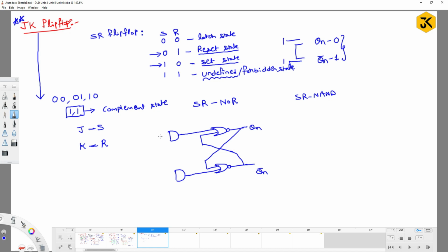We have seen the meaning of this also. As they are under single line control, meaning that at a single point we can control the entire structure. I can make it an enable signal or level signal, or I can make it an edge trigger signal. Depending upon the type of signal you pass here, we call it a latch or a flip-flop. So this is R and this is S. This is the SR flip-flop using NOR gates. We can simply call it an asynchronous SR flip-flop.